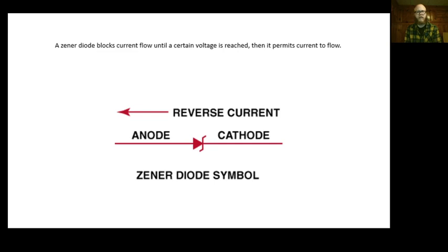This is a Zener diode. Your kit comes with one, but I played around with it, and the thing's so wimpy that you can overcome the reverse bias no problem. That being said, a Zener diode works like a regular diode, where it allows current to flow in one direction if we raise our voltage up to the point at which we can jump over that margin. But it'll also allow current to flow in the opposite direction if it's met with a big enough voltage. So let's say it takes half a volt to flow the normal way. It might take 40 volts to flow the opposite way.